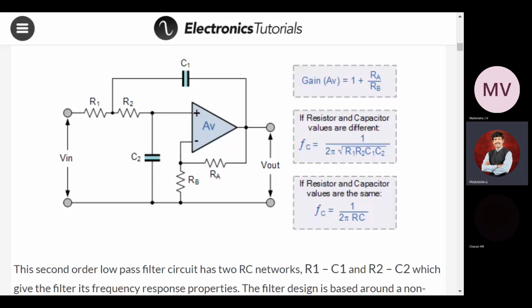Now what I will do is turn this regulator to get connected here. Once it is connected, the fan will rotate. Fan is going to rotate now because here it was an open circuit, which is a very high resistance. Here it is switched to the next position, where the resistance value is reduced from infinity to around 100 kilo ohm. Assume 100 kilo ohm.